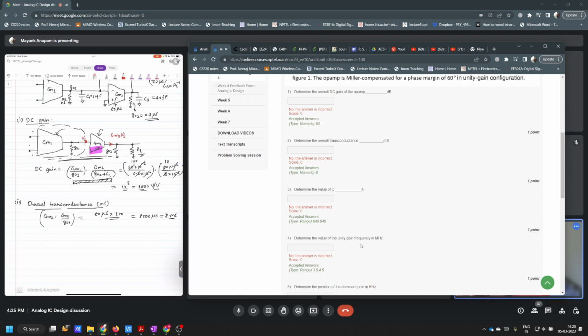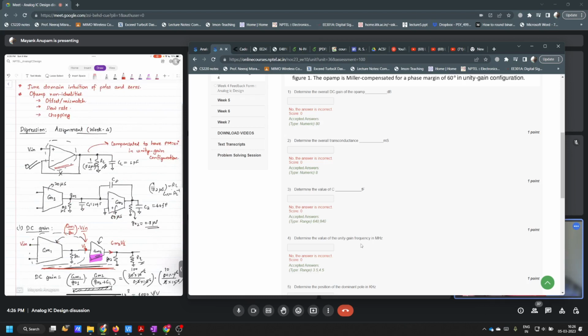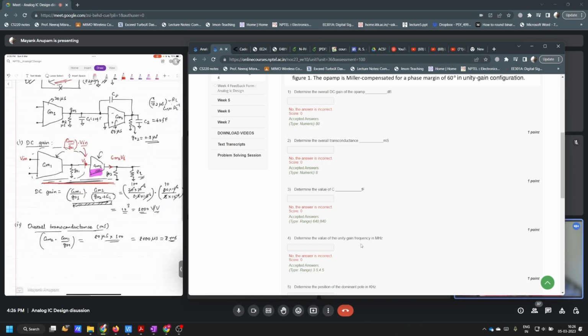And this voltage V1 will be equal to GM1 divided by small GO1, into whatever we apply here, V. Correct. So if you view this whole two-stage Miller compensated op amp as one block, as presented here, then when you apply an input Vin here, the current that will be pushed out will correspond to a GM which is amplified by this factor, isn't it?